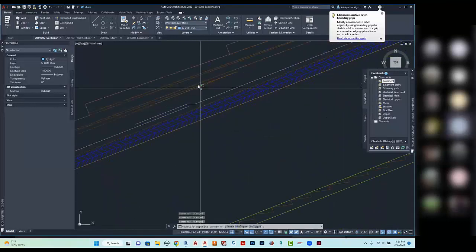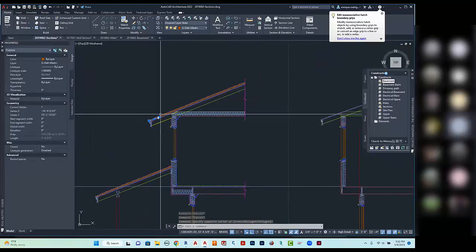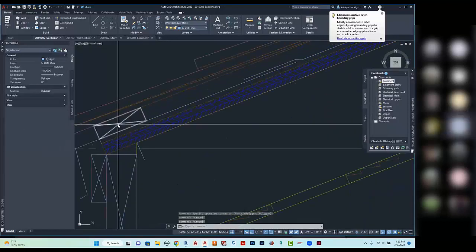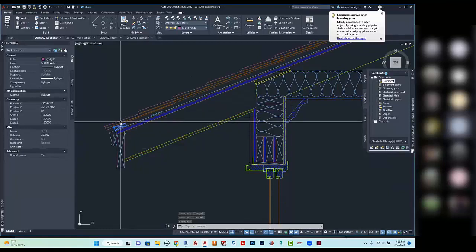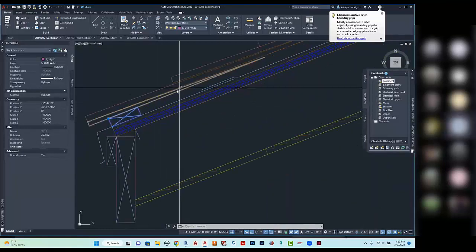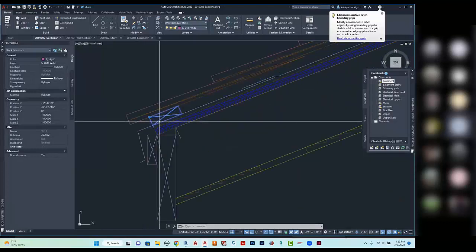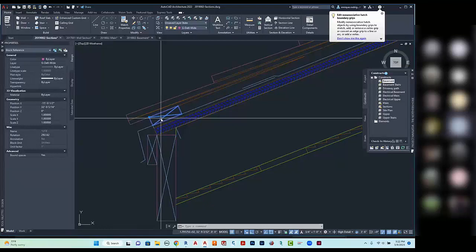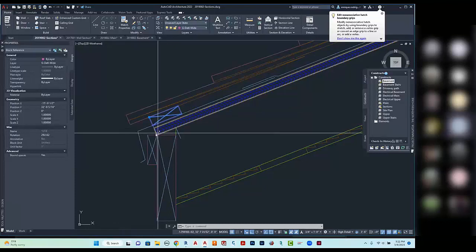top. This is actually one of the tiles that they include with the detail components. Now, this is another 1x3 in here because each tile rests on top of a previous tile with the exception of the last one at the edge. Sometimes you'll actually see roofs where that last tile is sloped down a little bit more than the other ones. But this is an element that can be used, should be perforated or should be spaced so that water can run past that or through it, etc.